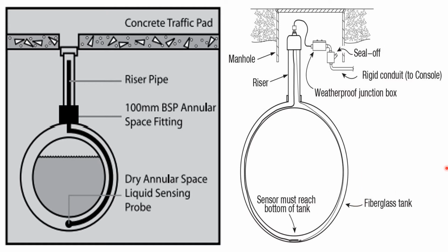Even though a lot of the tank pits act as big bathtubs, because the tank pit is usually made of a porous material like sand or pea gravel, and if the soil surrounding it is a lot more compact or less porous, then it will act like a big bathtub. So you'll have basically perched groundwater surrounding these tanks, and then this would work fine because water would drain from the outside into the tank and set this off, and you would know you had a problem with the secondary tank. Dry locations, that may not work so well.